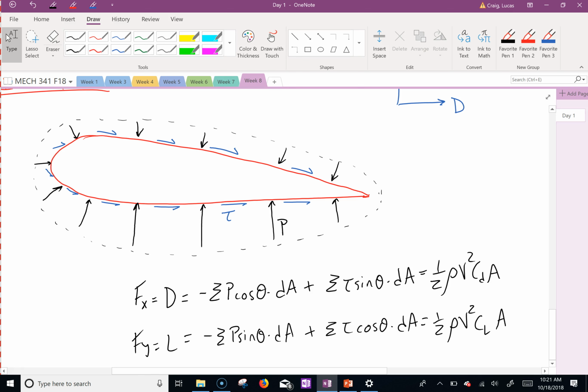For that project I've been talking about, I'm going to have you set up a homemade lift drag setup. We're going to use the one in there, but then we're going to take that one out and replace it with weights, with strings, and show you how you can do a mechanical force balance and still get the same results. And in order to get lift, where does the string need to come from, do you think? You want to hook up a string, you want to measure lift. That would be the bottom or the top, right? Drag would be either the front or the back.